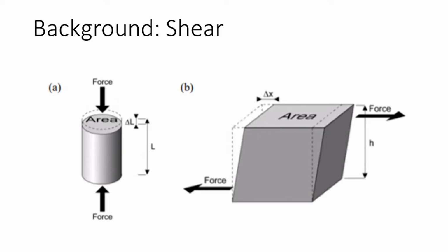For this lab, we'll be having you perform a series of tests designed to assess the behavior of a set of materials under shear loading. We previously tested samples in tension to learn a bit about axial stress, axial strain, and the modulus of elasticity for each material. This lab, we'll be looking at shear stress, shear strain, and the shear modulus, and comparing them to our previous experiment. As a reminder, shear stress occurs when a force is applied tangentially to the cross-section of a component. This creates a shearing action.